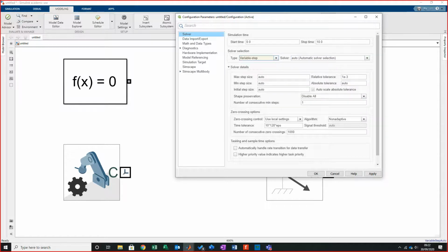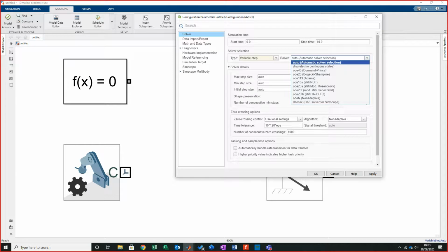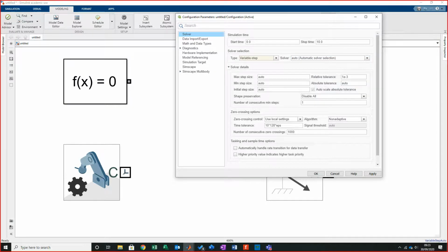So now if I go to variable time step, this is a method that's known as iterations. If you remember last week, we did the number of sequences within that coding, and that gave us that iterative response. What Matlab can actually do is use what are called predictor-corrector methods. In essence, it will rerun the simulation, let's just say, 8 times. It varies. Depending on the distance between two points, if they're very similar, it will lengthen the time step. If they're not very similar, it will shorten the time step, which makes it a variable time step method. But rather than being fixed to one solver method, it will run through all the ODE methods to try and find the most adequate solution for what we're looking for. This is a phenomenally powerful bit of kit.